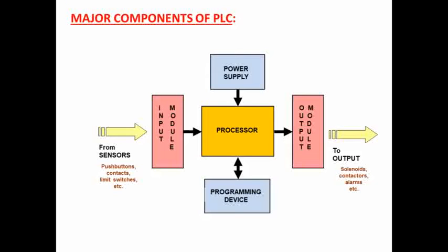So a digital I/O module performs four tasks electronically. First, it senses the presence or absence of an input signal at each of the input terminals. Secondly, it converts the input signal for high or on to a DC level usable by the module electronic circuit. And for a low or off input signal, no signal is converted, indicating it is off.